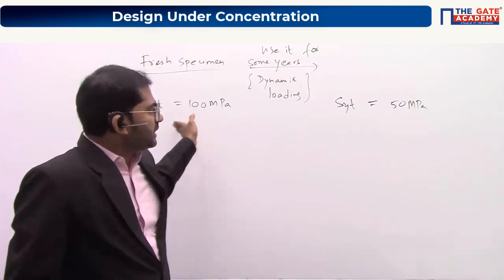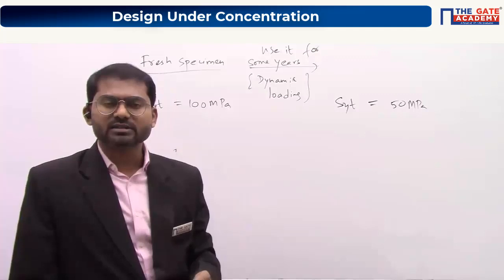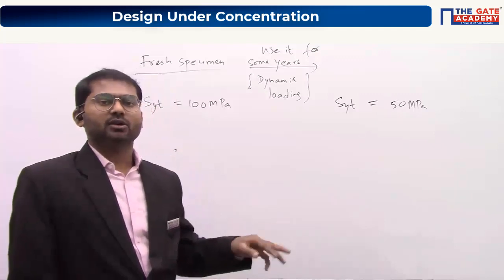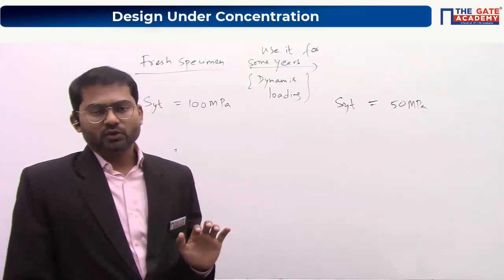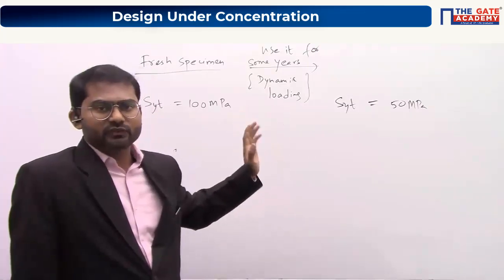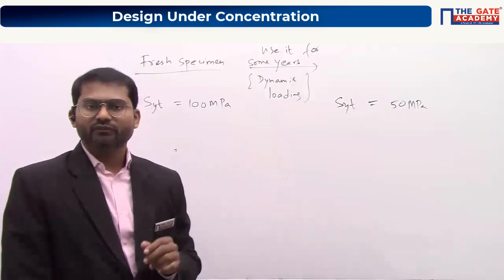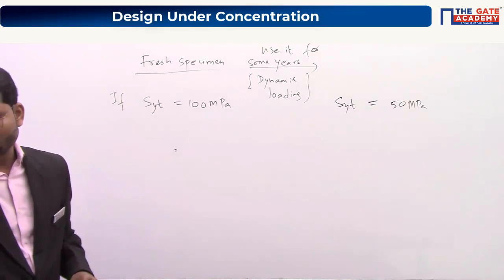This decrease of strength over time occurs only when there are dynamic loads. There are only two types of loads anyway, static and dynamic. Static loading will not cause any fatigue. Dynamic loading will give rise to fatigue. Understood? So this is the definition of fatigue here.